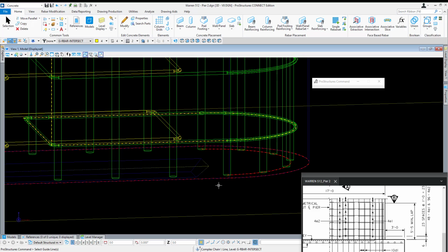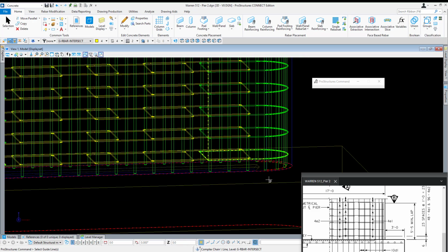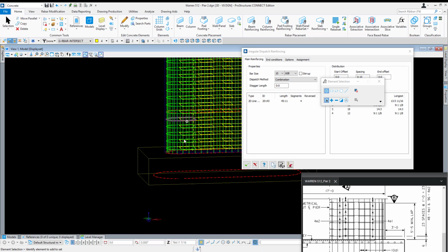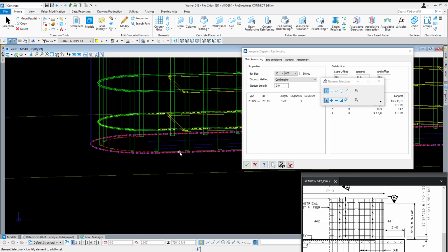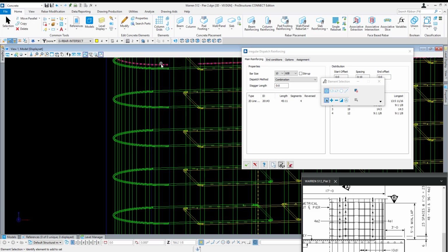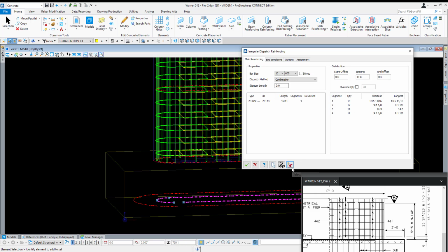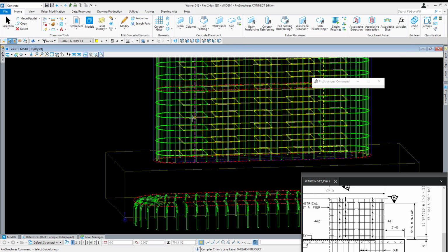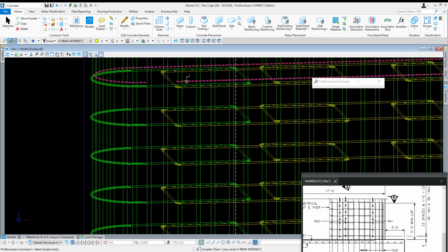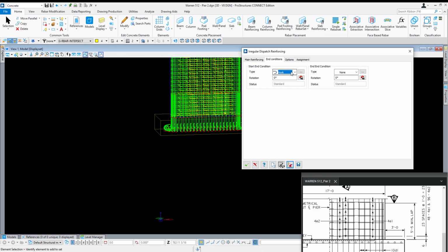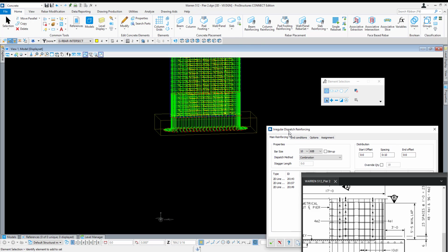And now I'm going to choose my guidelines. So first into my second, which is the interior one. Looks like I need to create that one real quick. For some reason it didn't get copied parallel, so I'm going to go ahead and copy this one down to here and continue picking second and then my third, and it looks like I have some end condition applied, so I'm going to go ahead and get rid of that and say none and check out my quantities here.